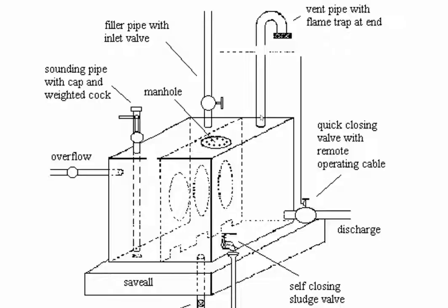We've also got to have a breather. So this is showing the upper deck, or uppermost continuous deck, or deck head. And here we have to have some way for the tank to breathe. So as we're filling the tank, it's got to displace the air that's in there. And as the tank's being emptied, as we're using fuel, it's got to allow air into the tank to fill that space, so we don't have it suck under a vacuum.